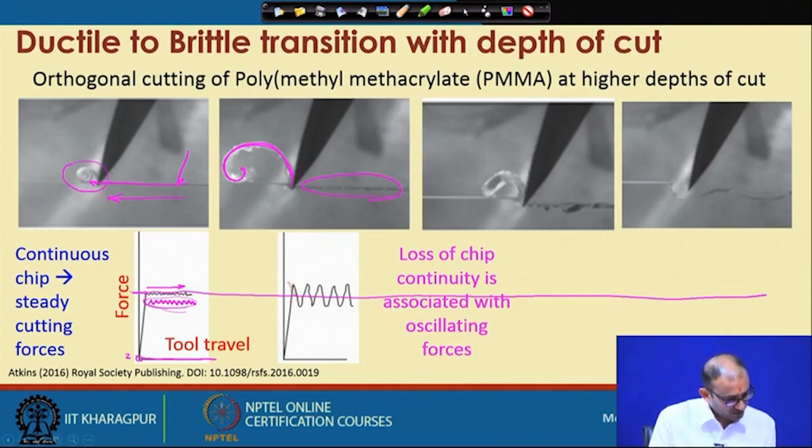The oscillation is very high, but still in full contact, meaning there is no open region in the signal. The amplitude is increased, which means a large variation in the forces. This variation also plays an important role in the life of the cutting tool as well as the workpiece material quality. So, let us see the third graph.